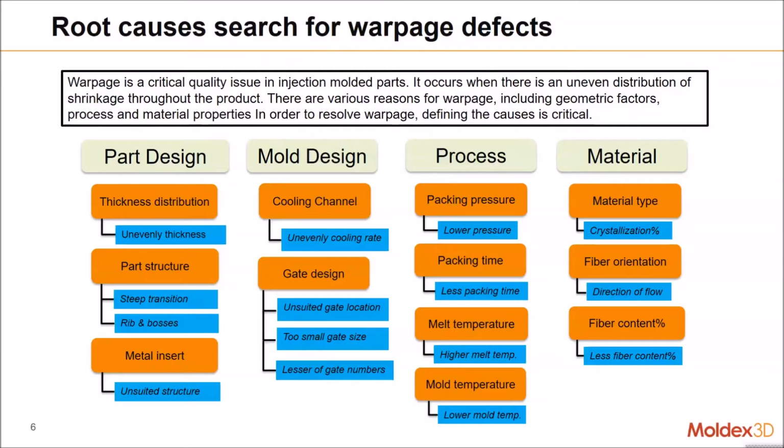And if fibers are aligned well, the shrinkage along the long axis becomes smaller. If not, the shrinkage will be similar in both directions. So you need to understand your flow direction in your mold. It can help you to predict the warpage behavior after demolding.